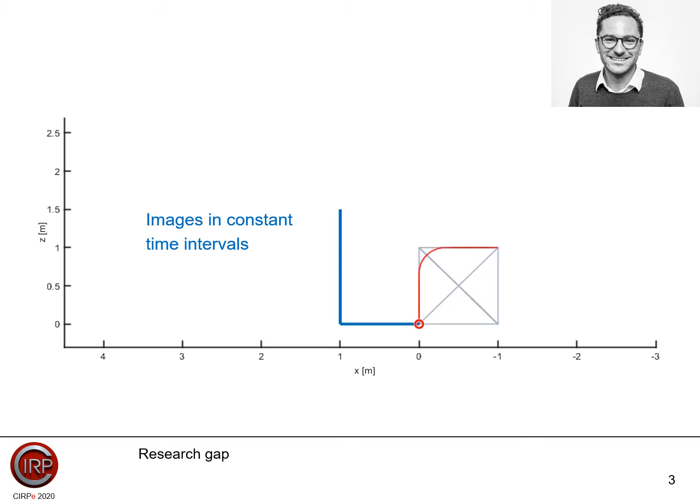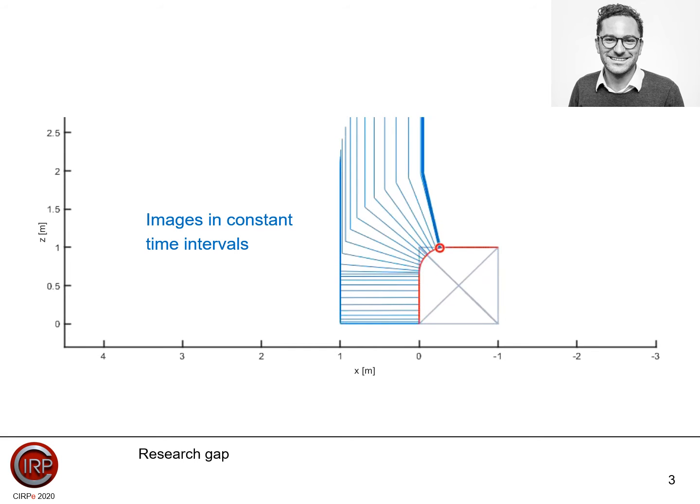A well-known approach in CNC applications to improve the motion in the corner is to round the path, as you can see here. This movement does not stay exactly on the trajectory which was defined before, but the TCP velocity stays high and the dynamics, so the jerks and all the kinematic variables, are not so high as to damage the kinematics.